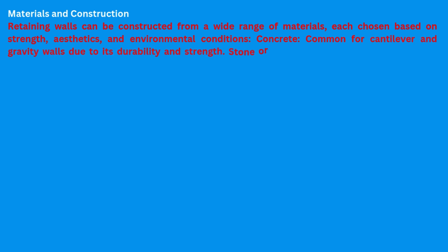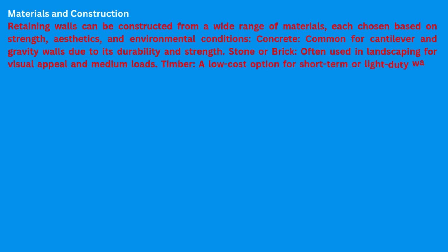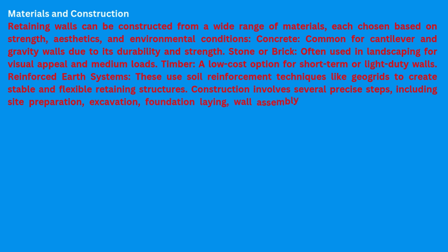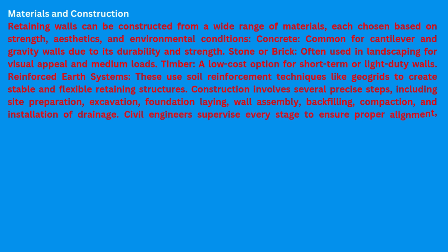Stone or brick. Often used in landscaping for visual appeal and medium loads. Timber. A low-cost option for short-term or light-duty walls. Reinforced earth systems. These use soil reinforcement techniques like geogrids to create stable and flexible retaining structures. Construction involves several precise steps, including site preparation, excavation, foundation laying, wall assembly, backfilling, compaction, and installation of drainage. Civil engineers supervise every stage to ensure proper alignment, structural integrity, and safety compliance.